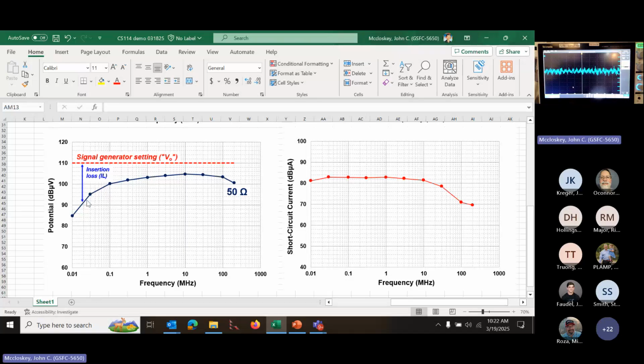This curve follows the contour of the limit line, which is defined as a pre-calibrated value into that 100 ohm calibration fixture. And this verification step tells you that you're getting a desired flat short circuit current, at least up to about 10 megahertz. This is actually pretty good.